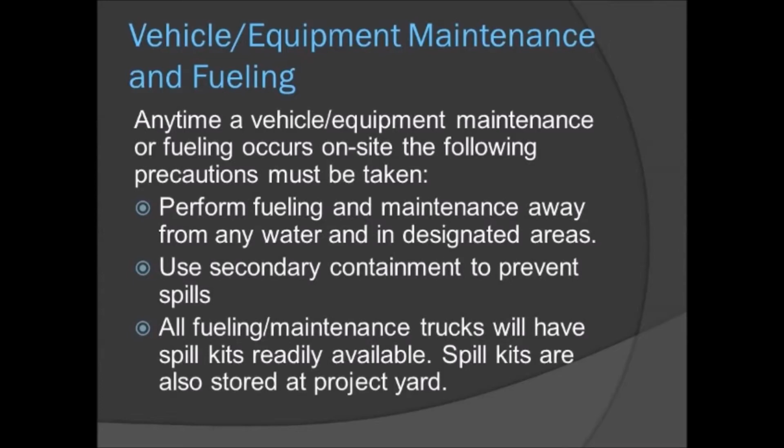Vehicle or equipment fueling and maintenance is the easiest way to release hazardous material into the environment. In order to alleviate this concern, all vehicle fueling and maintenance must be performed away from water, must use secondary containment to prevent spills, and have spill kits and absorbent material available in case of spill.